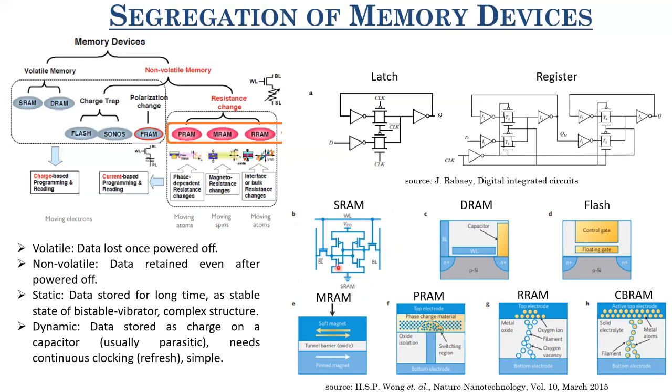Not a latch, but a flip-flop. We can call it a flip-flop. So it's a cross-coupled inverter pair with 2 access transistors. That is a total of 6 transistors. This is the standard industry SRAM cell, which is 6 transistor.